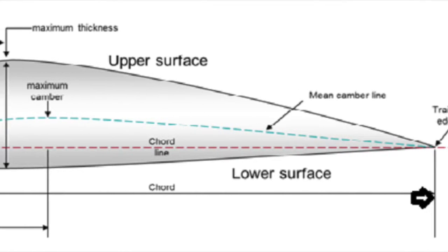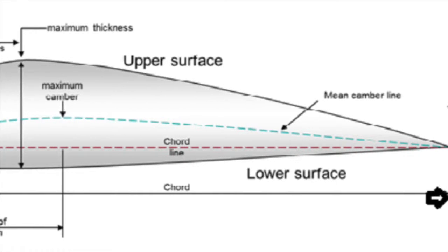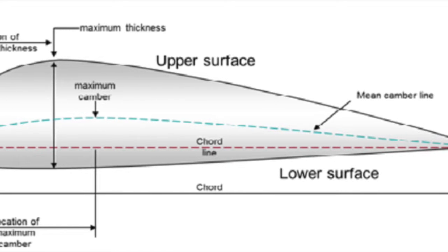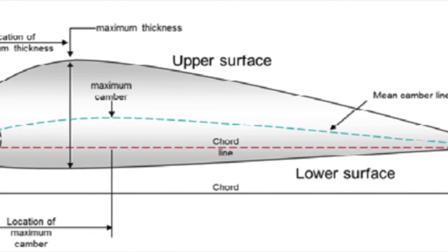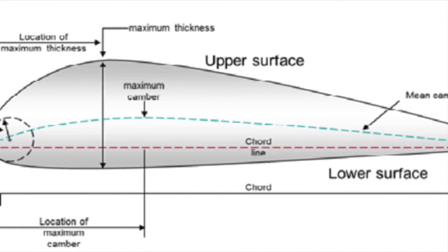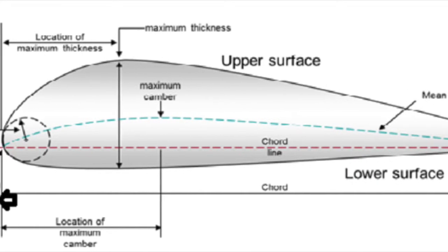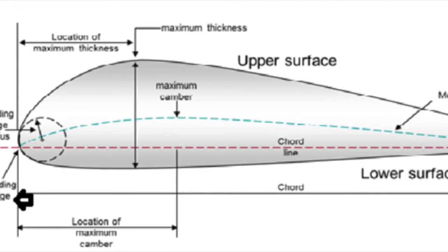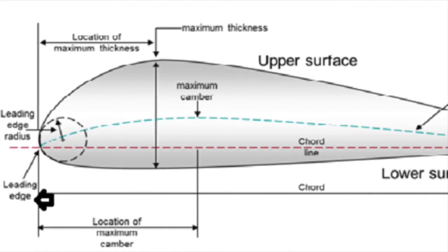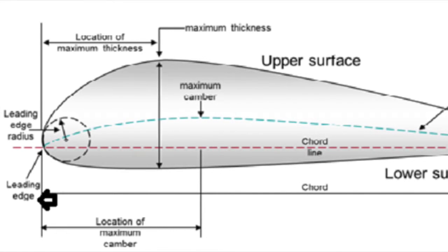The foil used for the Mustang had a thickness ratio of 15.1% at the wing root. The tip ratio was 11.4% at the 50% chord line. These numbers provided the maximum thickness area at 40% from the edge of the wing of the aircraft and resulted in a small negative pressure gradient over most of the wing surface.